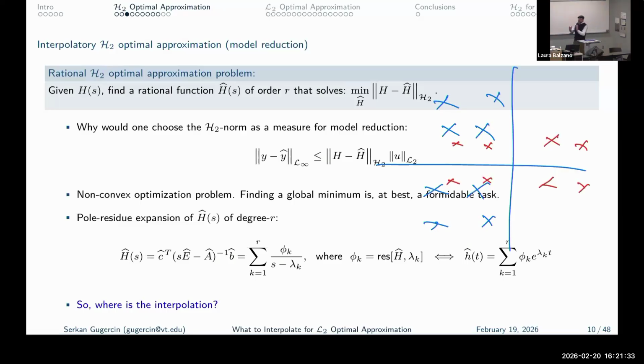The reduced poles are definitely not going to exactly approximate the full poles, but probably they're going to be in a kind of similar domain. So if you have an idea where your important poles are, you just initiate your algorithm there. Somehow the algorithm finds its way to a good local optimum, but I can never guarantee global. But really, coming from the underlying structure, it has been pretty robust to this.